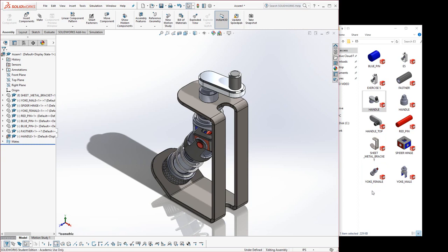The first place it looks is the folder it's in. The second place it looks is the tag that is internal on the parts, and it goes back, or references, I should say. The assembly tells it where those parts should be. If those parts are no longer there, then it's going to get lost and it's going to ask you to browse for them. So just be careful when you are sending this assembly. Send it as a group.